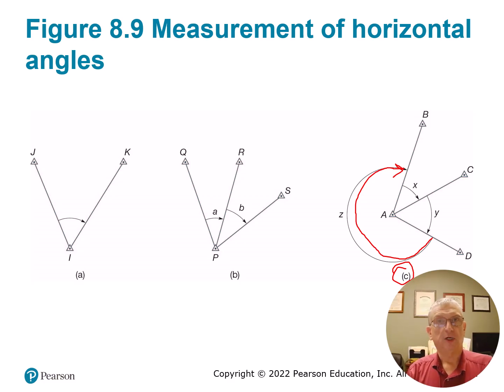And if you get redundant observations, your most probable true value is the mean of those. So if you double an angle, you talked about the horizontal plate. There used to be a bottom plate and a top plate, and you could set the backsight to 0. Let's say that you turn an angle of 30. You would leave that angle totally unaltered, loosen the bottom plate, and the instrument's just turning free, and it's still showing you 30 degrees.